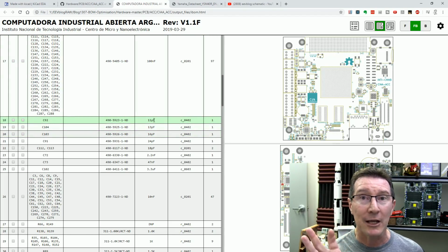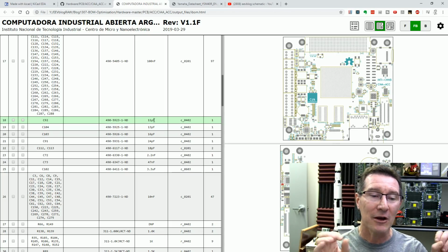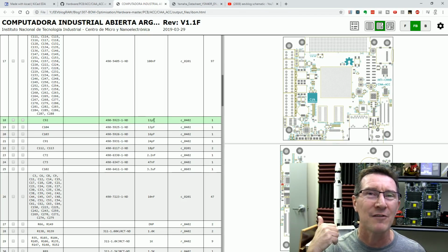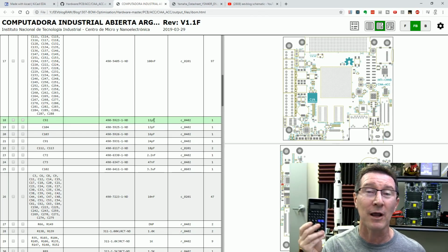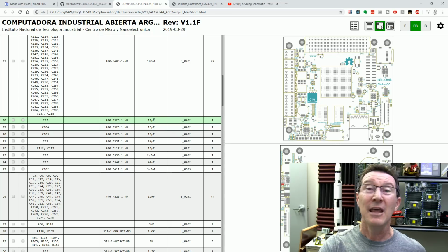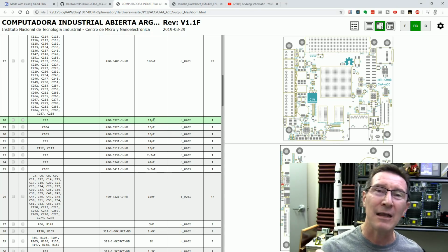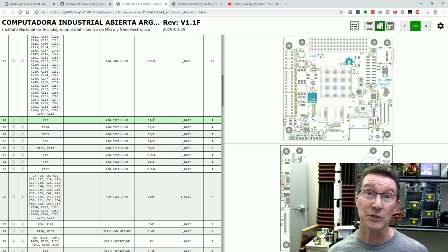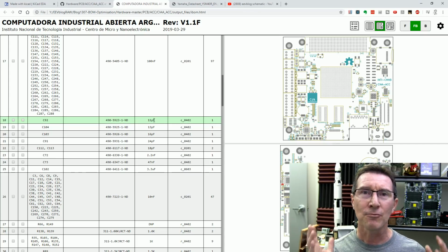Now, look, if you're doing a complex RF design or something like that, then yeah, okay, that could matter. But in a lot of cases, you're just going to choose these values because they came out of an application note, or it's what came out of your calculator, for example. You might want, okay, I want like a 1 megahertz filter. You do your calculations and it comes out to 11 picofarads or 11 nanofarads or whatever it is, and a resistor value of 6.25K. So you choose the closest E96 preferred value to that. Well, you don't really have to.